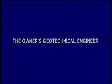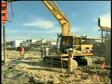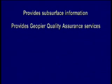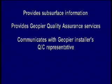The owner's geotechnical engineer. The geotechnical engineering firm of record working for the owner is normally responsible for the following: providing subsurface information for conditions within the Geopier reinforced portions of the site, providing a quality assurance representative at the site during installation of Geopier elements and during performance of any modulus load tests, communicating closely with the Geopier installer's quality control representative so that both parties agree on the data obtained related to Geopier installations, including verifying correct drilling depths, confirming Geopier installation procedures, and recording number of Geopier lifts.